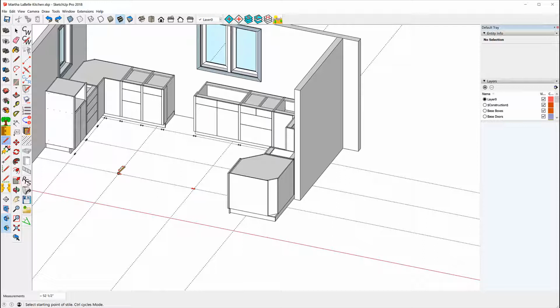I have a choice. I can use my centering tool between the outside markers or the inside markers. It's usually best practice to use the inside markers because this style and this style might be different types of styles, and therefore they might actually be different widths. So if I chose the outside markers, I'd get a center that didn't give me the same opening in these two cabinets.